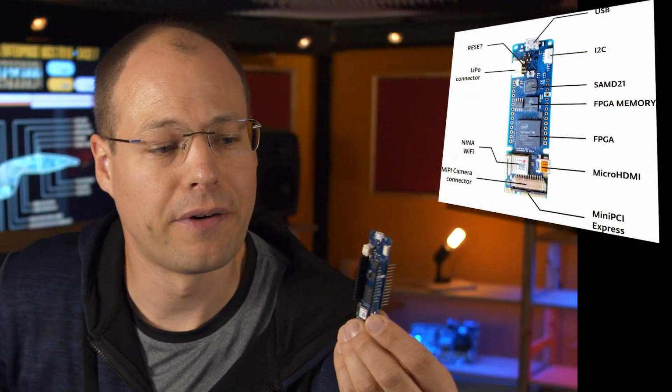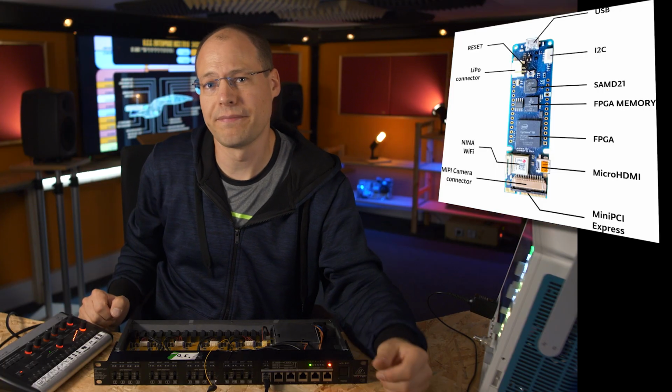Now that we have access to these serial signals, we can make more of them. In my last YouTube video I had already introduced this Arduino here, the MKR Vidor 4000. We simply use this mix of microcontroller and FPGA to build a simple digital audio mixer with 16 channels out of it. So first we need to make a hardware connection between this half-defective P16-I here and our Arduino. Both obviously operate at 3.3 volt level, which allows us to easily make a connection directly.